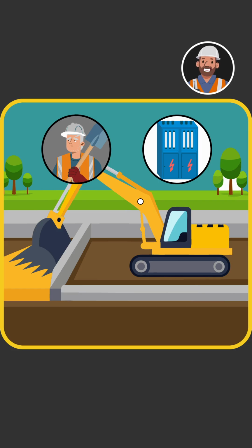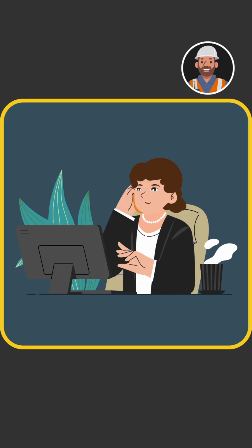Sand surrounds marker tape. If any service is uncovered, stop immediately and contact the utility company. Always assume services are live unless confirmed otherwise by the owner.